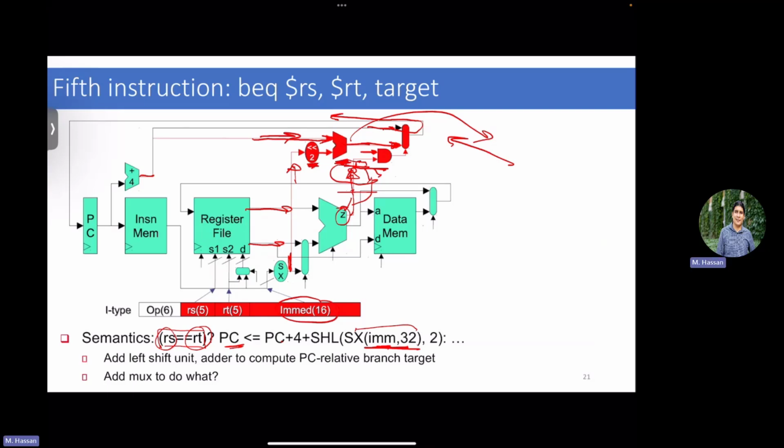Is that going through the shift register? Or is it just direct? Yeah, no, it's not going through the shift register. You simply take the upper 4 bits of your program counter register and augment it. So here, that path is only 28 bits. Its width is 28, right? Because remember, we had 26 plus shifting by 2, so it's 28. So you still need 4 bits from the most significant bits of the program counter.